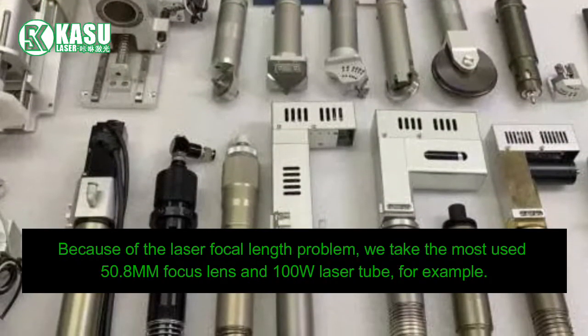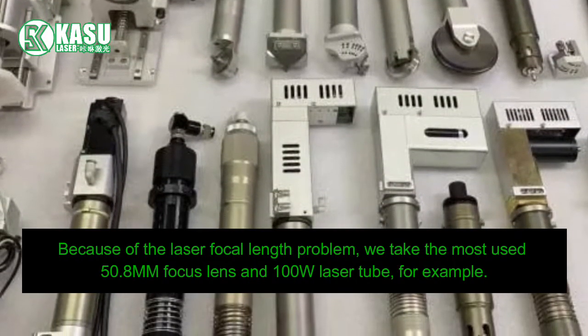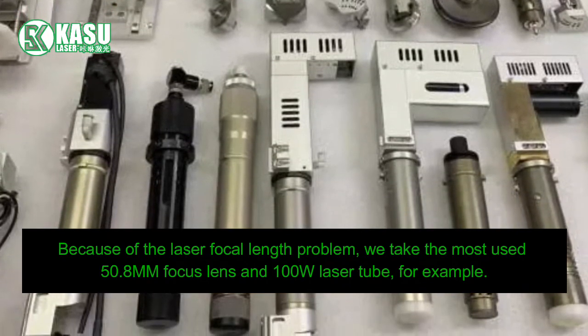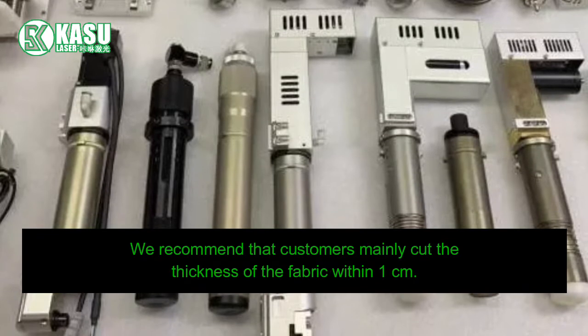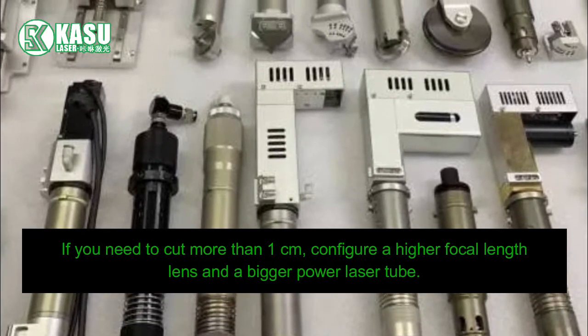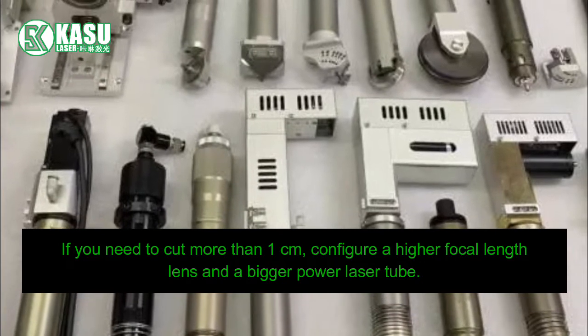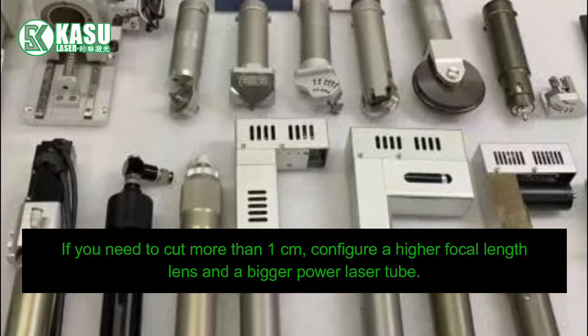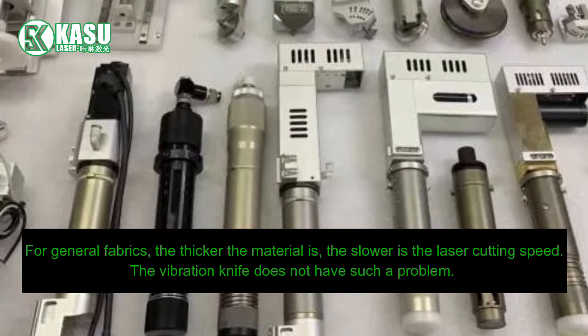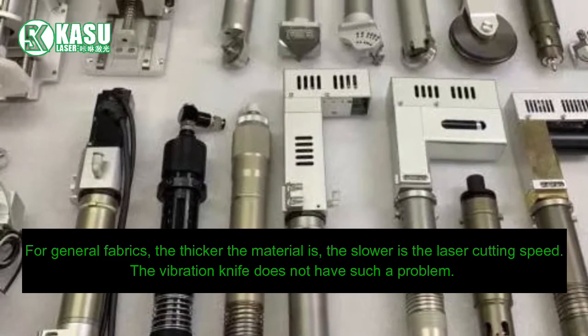Because of the laser focal length problem, we take the most used 50.8 mm focus lens and 100W laser tube, for example. We recommend that customers mainly cut the thickness of the fabric within 1 centimeter. If you need to cut more than 1 centimeter, configure a higher focal length lens and a bigger power laser tube. For general fabrics, the thicker the material is, the slower is the laser cutting speed.